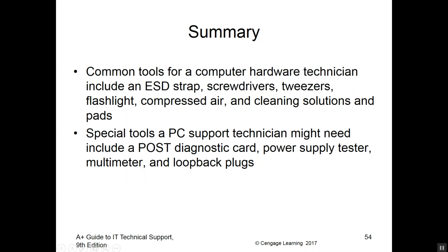Now, common tools for a computer hardware technician include an ESD strap, both straight and Phillips head screwdrivers, and tweezers. Now those tweezers were insulated. Flashlight, compressed air, and cleaning solutions and pads. Always be careful when you're using cleaning solutions because some of them are more corrosive than others. And if we're not sure about what we're doing, it could take the letters right off your keyboard or put a gray haze over a monitor. And that's not something that's worth the aggravation. So always know what we're doing before we go to use any kind of solution.